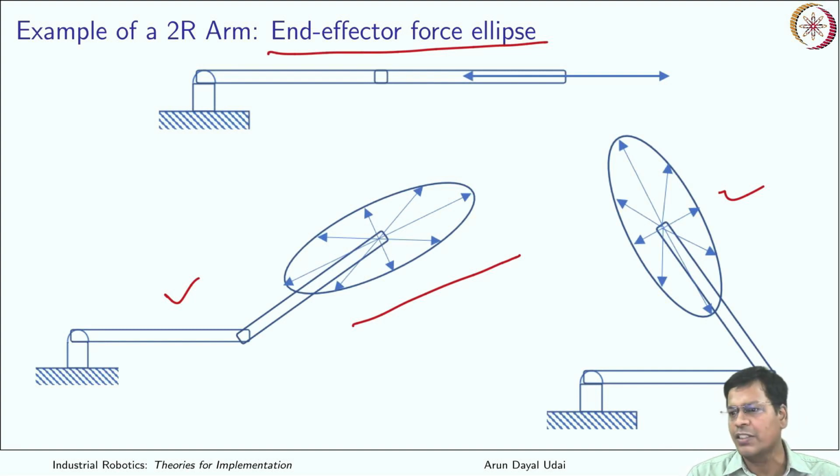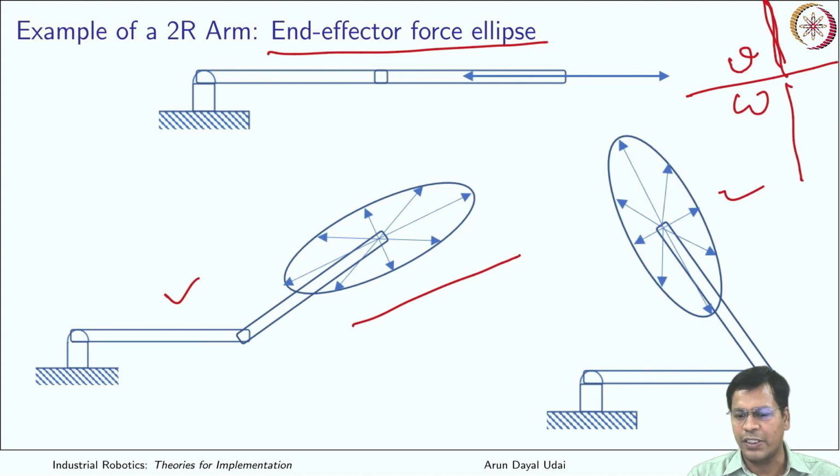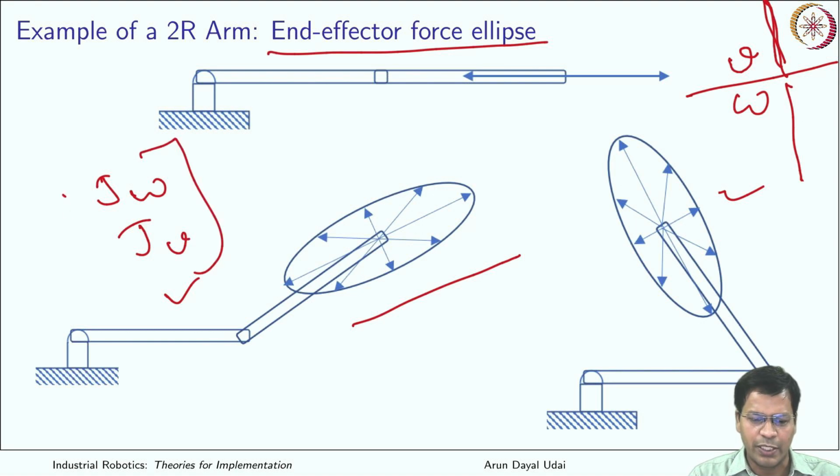Even for a 6 degrees of freedom system, there are two partitions: linear velocity and angular velocity. So three for linear translational velocity, and three for angular velocity spaces. The Jacobian will be 6 cross 6 in that case, with J omega and Jv, as you know very well.